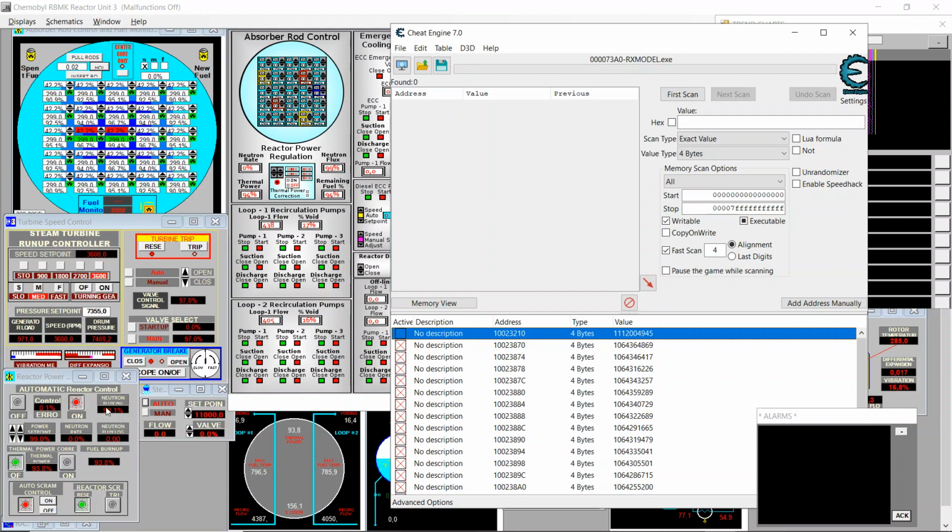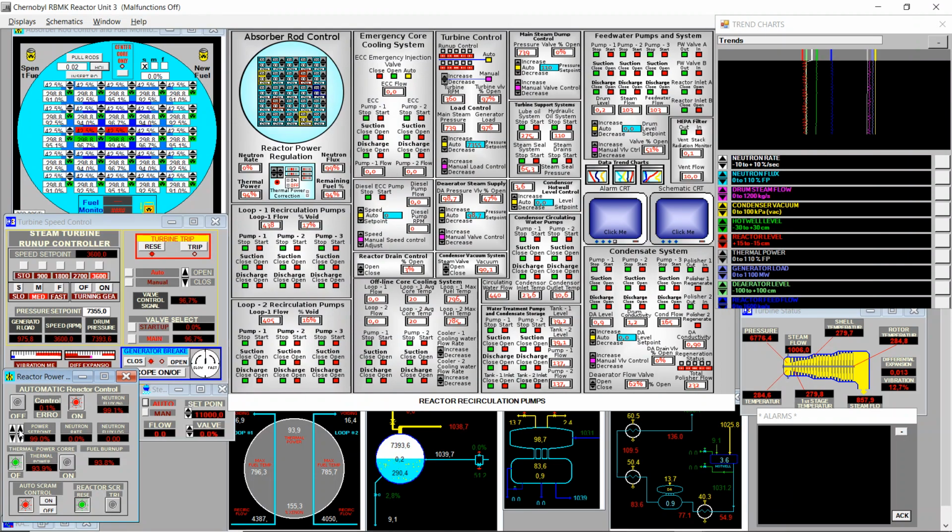If we wait a long enough time and we reach a new thermal power equal to neutron flux and a xenon concentration asymptotic, which doesn't change anymore, I expect to have a power set point which is the same as the neutron flux. For the moment we cannot set the power set point to 100 because this would mean a neutron flux of 100.1%. This is a meltdown of the reactor. So I will increase the last step, which is 99.5, and we get a neutron flux of 99.6.